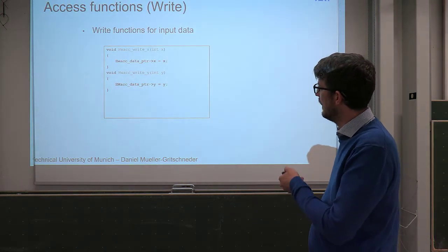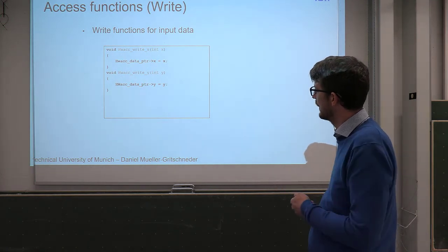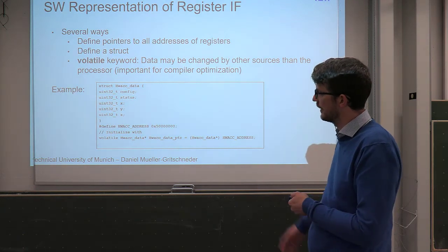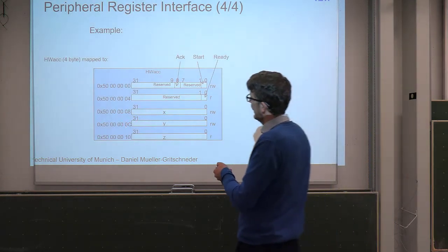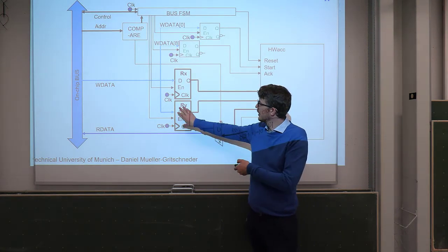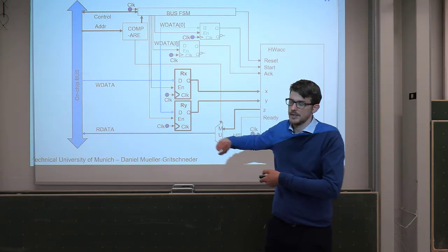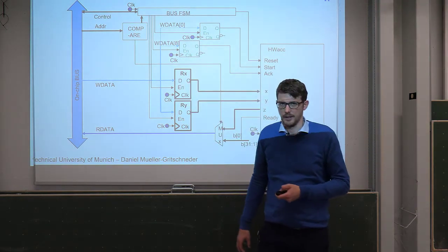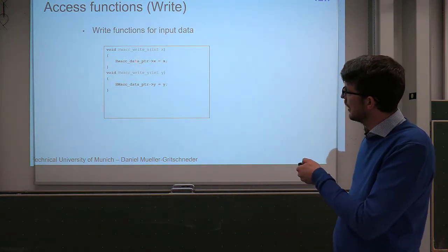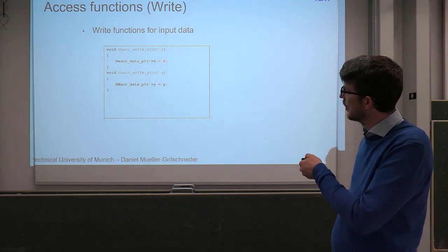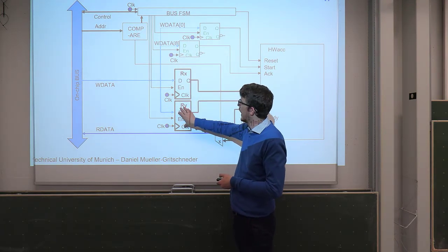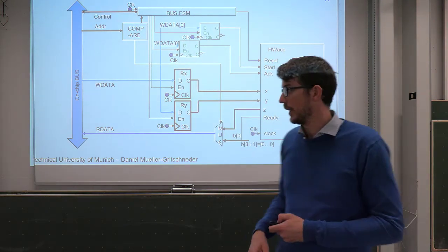And the same, of course, with y. This is the same thing, but the pointer of y is another offset. So y is the next element in the struct, and this means the offset is C. So the offset is C, and then it knows this is y, and this y data port would go into this register because this register has the address with offset C. Right? This register has the address with offset 8. So if you do this, and you call this one with an integer value and this one with an integer value, then we will have the value for x in this register and the value for y in this register. So this is the first thing you're doing.